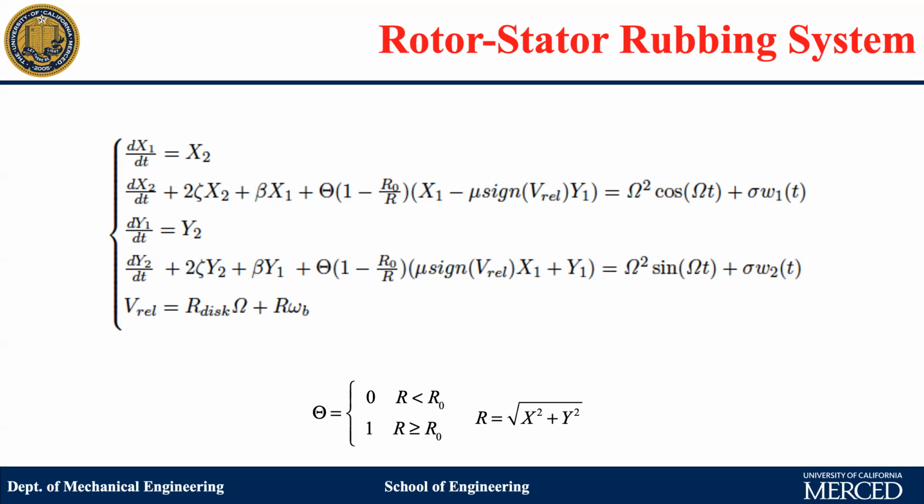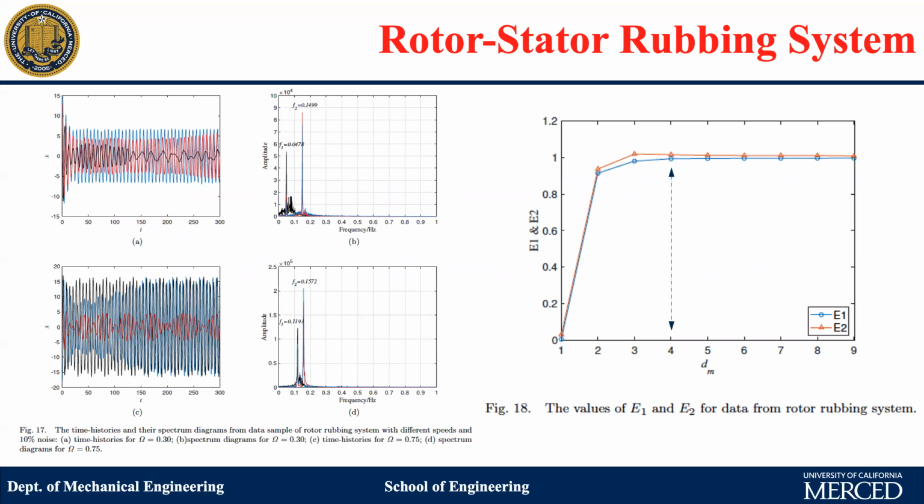In this example, we simulate the data. We insert random noise into the equations of motion and apply harmonic excitations, so we collect a lot of data from the system. Now we do FFT and find the resonant frequencies of the system. This system has 2 degrees of freedom for the linear states, so you see 2 clear peaks there. You can use those numbers to specify a fundamental frequency of the system, and that may serve as a mapping step for you.